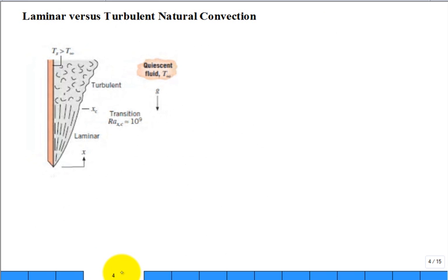All right. Well, we talked about setting up a coordinate system coming out from the tip. We have y, we have x going up from the tip. We talk about typically a hot surface, Ts is greater than T infinity, and gravity is acting, and the colder fluid will sink, the warmer fluid will rise, and so you get the development of a laminar boundary layer.